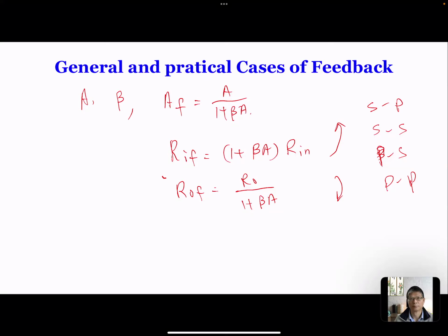So the idea is that you can't put two voltage sources in parallel. If you put them in parallel, the slight voltage difference will cause a circulating current. So voltage is rarely in parallel. Of course, we do put batteries in parallel, so it happens. But in electronic design, you rarely put voltage sources in parallel. You don't put current sources in series either. So that's how it works.